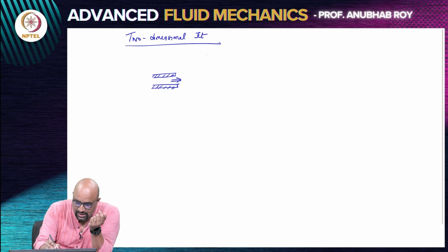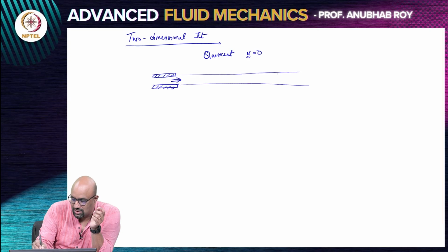Now the fluid outside is actually quiescent, it's still. There is no motion for the fluid outside. You are injecting fluid into this system. Now if this problem was exactly an inviscid problem, then what would happen is you would have this thin strip of fluid if you are injecting with some velocity profile, and I will just consider, let's say, this velocity profile is uniform.